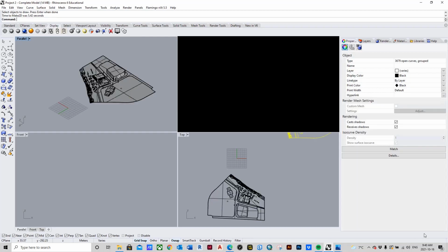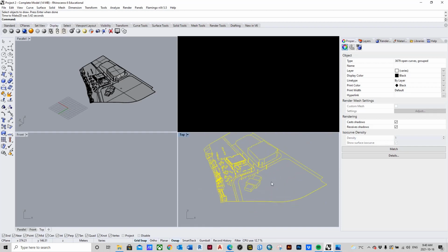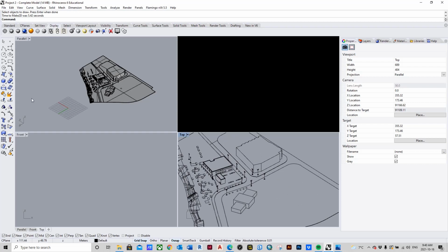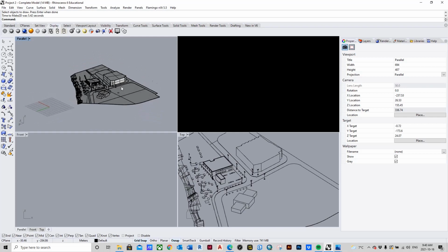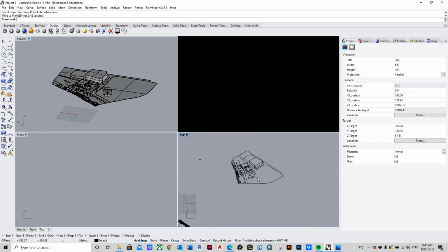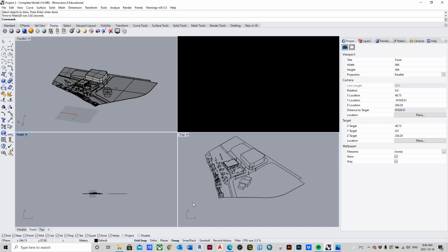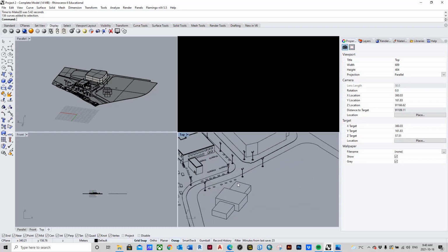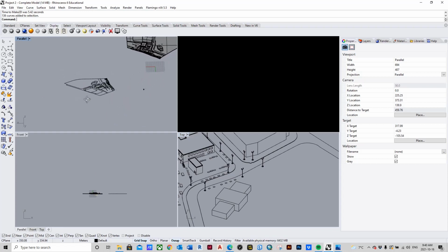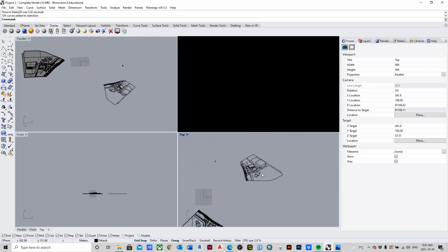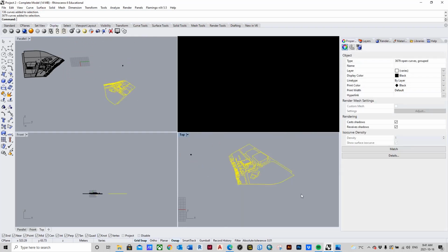We can see here it's got a loading bar. Now look at this. Everything it just produced, it produces over here in the top window. But check this out. While this is the actual physically developed model, these here are just the lines for whatever we just exported as Make2D. So you can see here, let's zoom out a little bit. It looks kind of nonsensical from this perspective, but from the top view, this is essentially a pretty good demarcation of exactly what we just wanted to export.